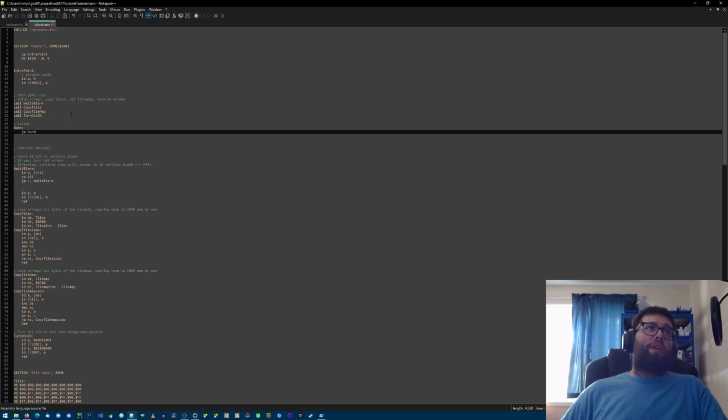During that blanking period, you are free to write to the screen, make calls to the screen. And what we want to do is actually turn off the screen because if we try to do anything while the screen, like if we try to shut it off before it gets to the V blanking range, we can actually damage the hardware.